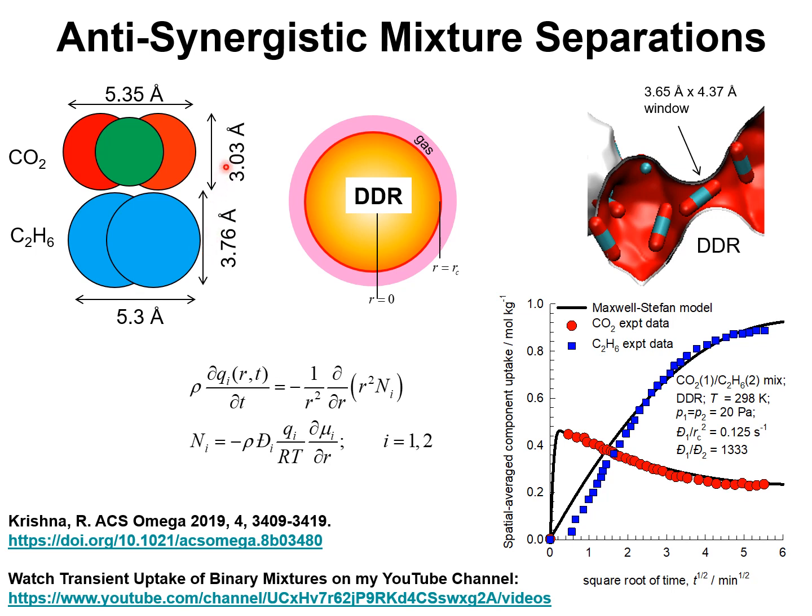strategy relies on anti-synergy between mixture adsorption and diffusion in microporous crystalline materials. In particular, I'd like to consider separations using DDR zeolite that consists of cages separated by narrow windows with an aperture size of 3.65 angstrom. The shortest aperture distance and the longest distance is 4.37 angstrom.